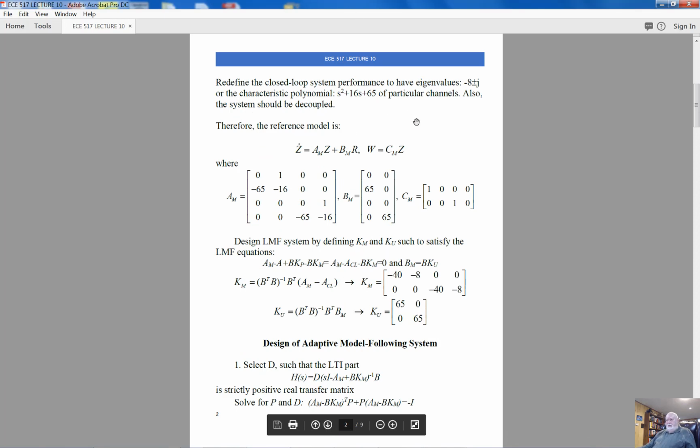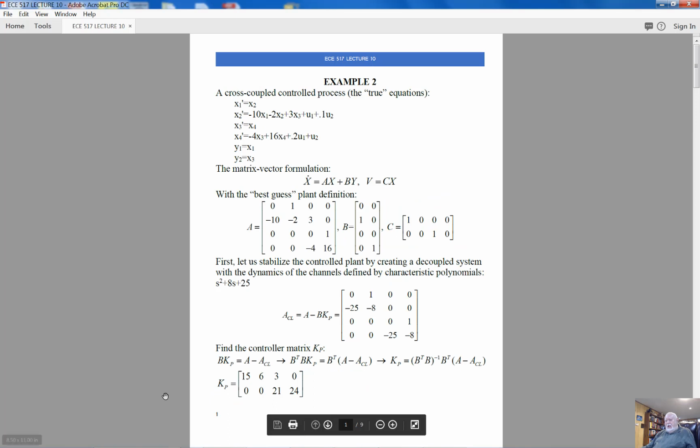What I will do now, I effectively achieved the decoupling behavior. How do I know I achieved the decoupling behavior? Well, if you want, I know matrix Kp, I know matrix A, I know matrix B. A minus B times Kp will be exactly this matrix. Our system will become a system with a block diagonal fundamental matrix. This matrix is surely decoupled, or the system is surely decoupled.